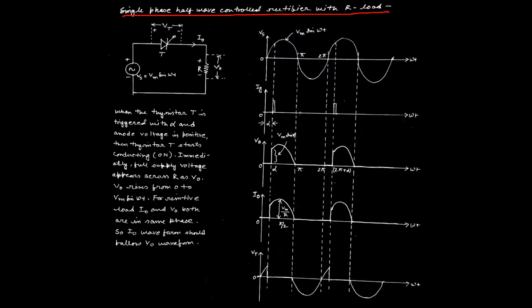Now from this operation we can find the average value and the RMS value. Okay, because it will give us a pulsating DC like this, the output voltage. That means as it is a rectifier operation, AC is converted into pulsating DC. That is why we are going to calculate the RMS value as well as the average value of the waveform that appears across the load, or V0.